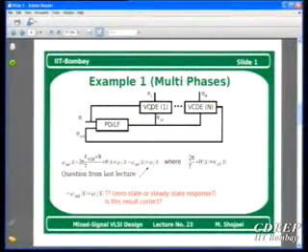But in that case, we didn't have 2 inputs to the loop. Look, here the difference is you have 2 inputs to the loop. One goes to the delay element, one goes directly to the phase detector. There we didn't have this problem because we have just 1 input and then the entire feed-forward path was here after the loop filter. But here now actually we have 2 paths, right?